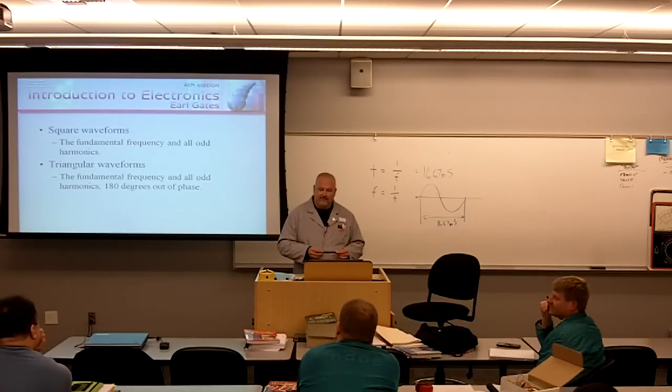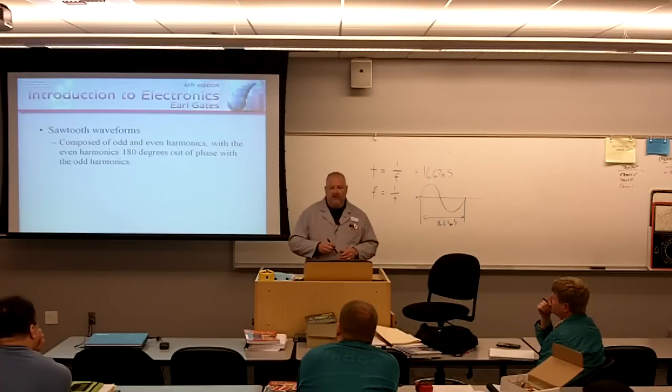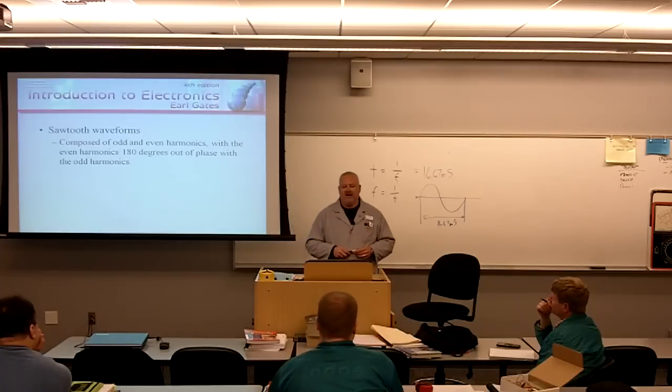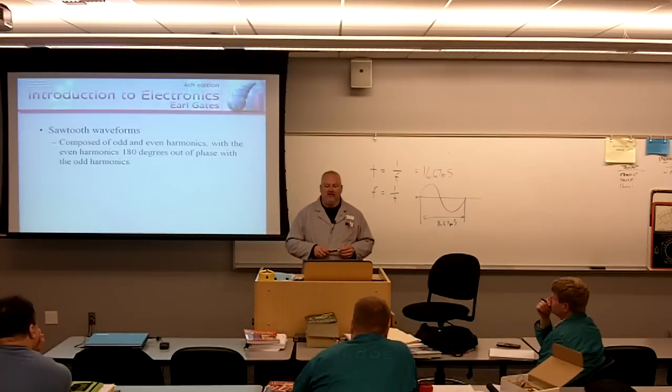So do the harmonics have the same shape as whatever the waveform is, just less of an amplitude? Yep. Less of an amplitude, but yeah, the same shape. It's just the same frequency. Triangular waveform is made of the fundamental frequency and all odd harmonics 180 degrees out of phase. Fundamental frequency and all odd harmonics 180 out of phase. Sawtooth waveforms are composed of odd and even harmonics, with the even harmonics 180 degrees out of phase with the odd harmonics.